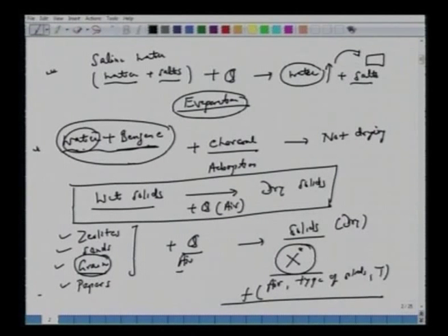Now from the mechanistic point of view, if you are careful, drying is about heat and mass transport. That's the main difference we had between drying and the other unit operations. If you recall previous unit operations, say absorption, distillation, adsorption, extraction, in most of them, other than distillation, we did not have any energy balance or enthalpy balance.